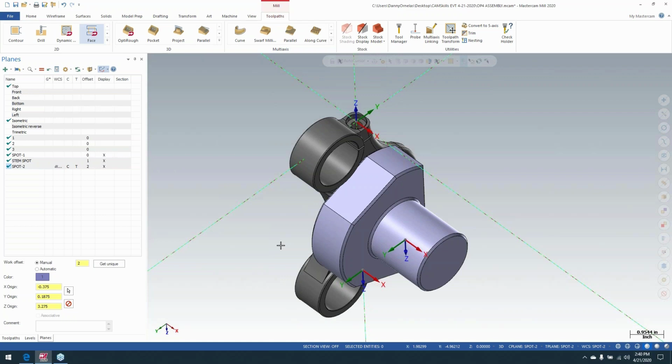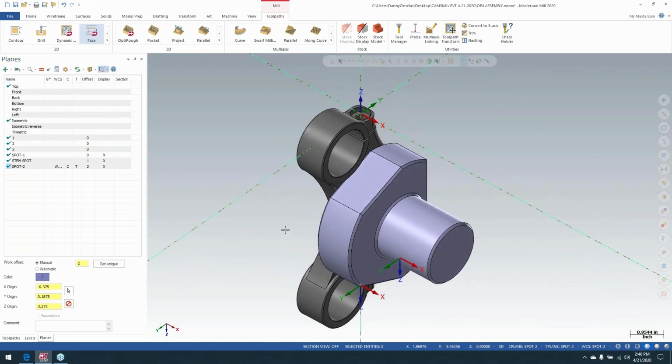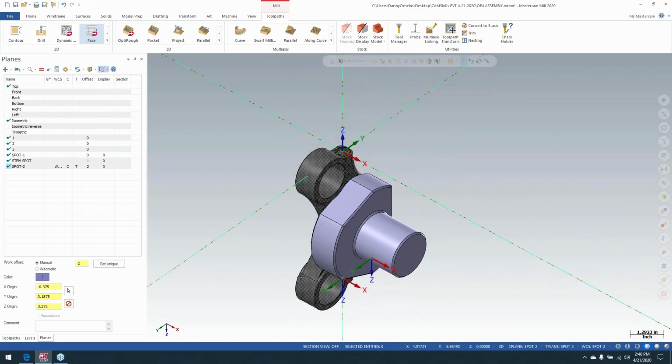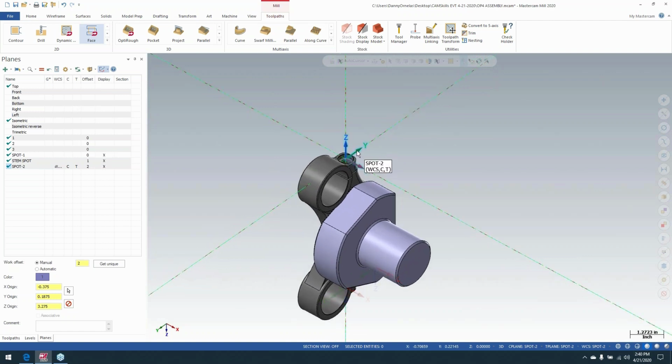display our work offsets. And this is something whether you're doing a 4-axis machine or a 5-axis machine, let's say you have a Haas UMC 750 or a Mori, like an M5500, something like that. There's all different kinds. Let's say you have just a regular 5-axis with a trunnion, okay? To get the trunnion to rotate with the bias towards you, you always have to keep in mind that the Y always points toward the trunnion, okay?